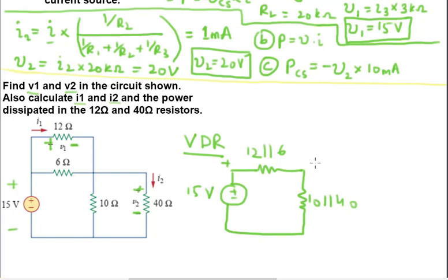So this voltage would be V1, this voltage would be V2, and the current is going to be I. And now apply the voltage division rule to these two series connected resistors. Once you do that, the problem becomes very simple, because V1 is the voltage that is present over here, and it is the same as this V1.